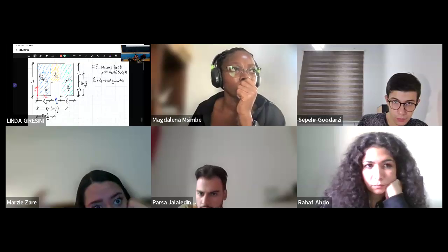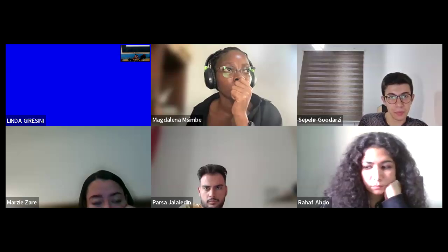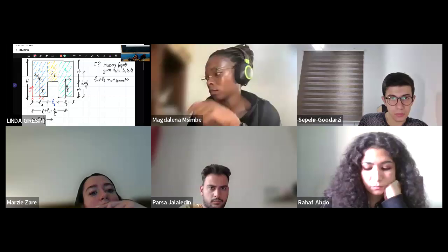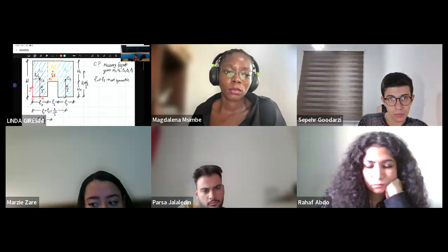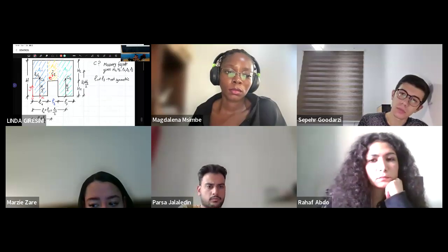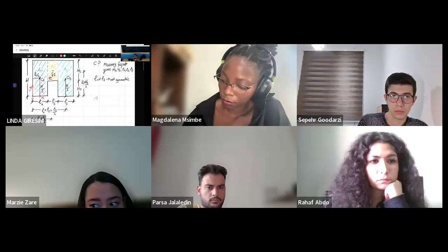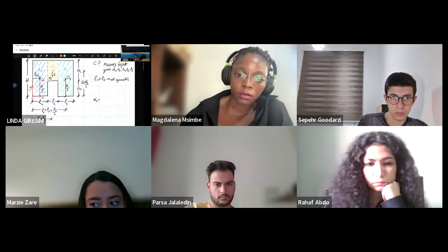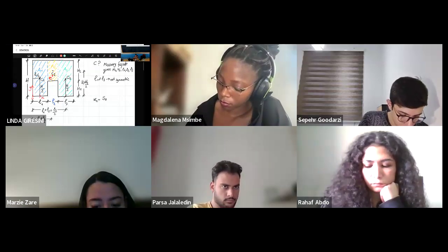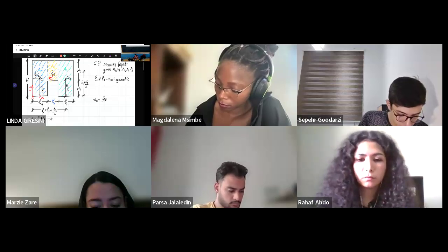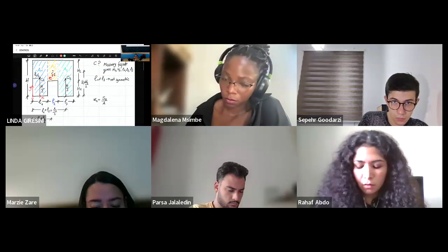So now you want to find the centroid. Probably, due to the fact that we removed the opening portion, it will be higher than the previous one. So it will be probably here, the centroid. And the formulas are, let's go for XC. XC is the static moment with respect to Y divided by the total area of your geometrical shape.